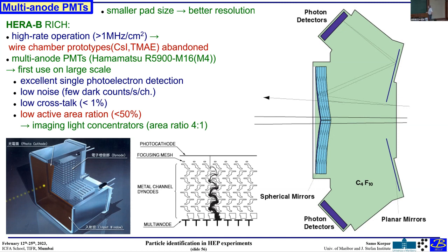At that time, Hamamatsu came out with this metal channel plate diode structure, which allowed a segmented anode readout at the end. So there were multi-anodes. These are very small machined diodes, basically an array of diodes, where the photoelectron comes in and then stays trapped within one channel and goes down. So it has a very nice separation between the channels. The previous multi-anodes from Philips had a very large crosstalk around the pads, and this structure allows a very limited avalanche or multiplication chain.